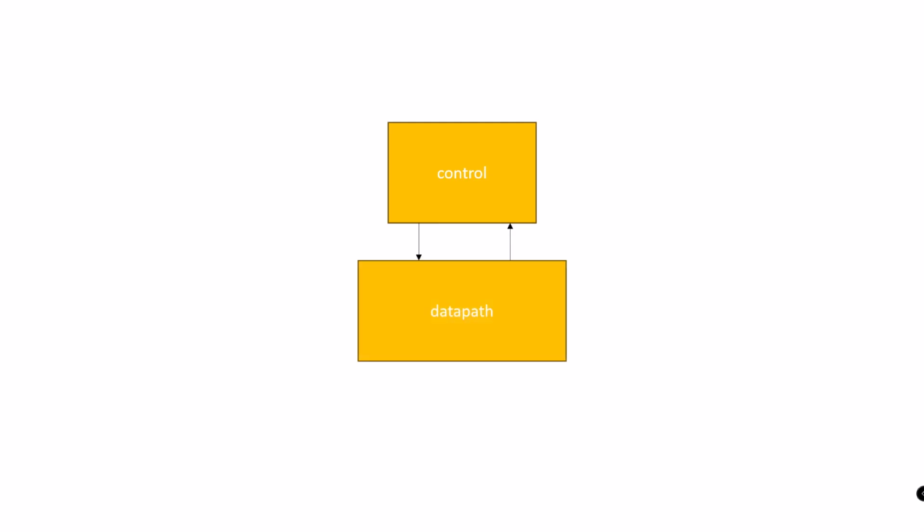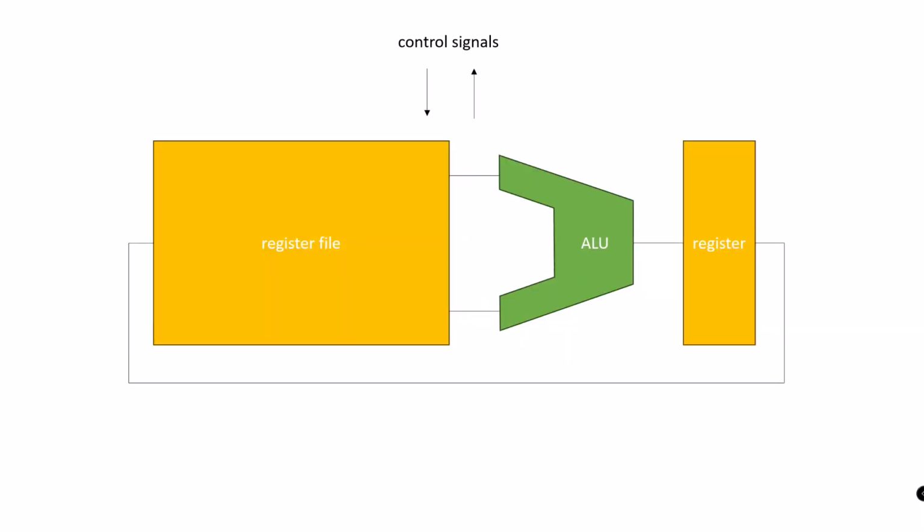This datapath controller system is divided into two components. A datapath provides registers and data operations. A controller manages the operation of the datapath to perform the desired functions. This division of labor uses divide and conquer to improve the design. Controller FSMs use less structured logic. On the other hand, datapaths often perform regular operations like addition that call for different design techniques.